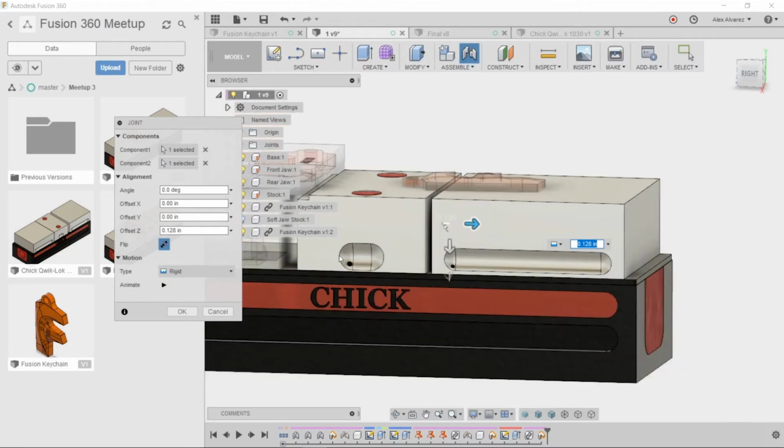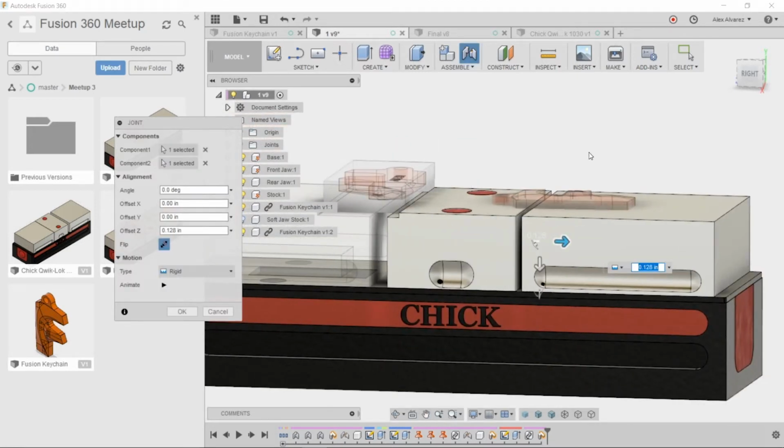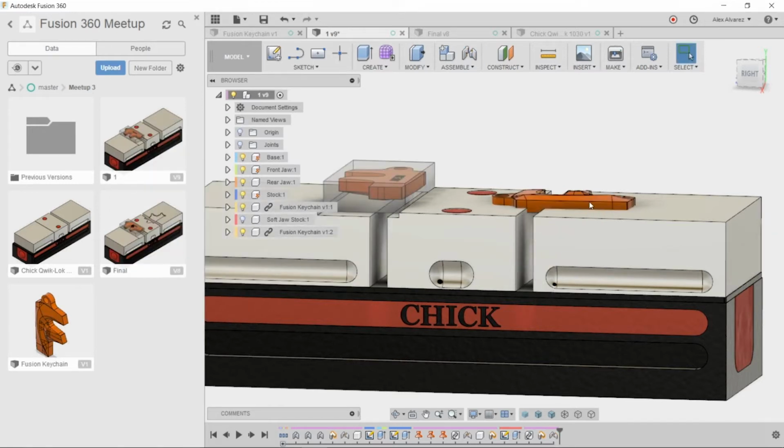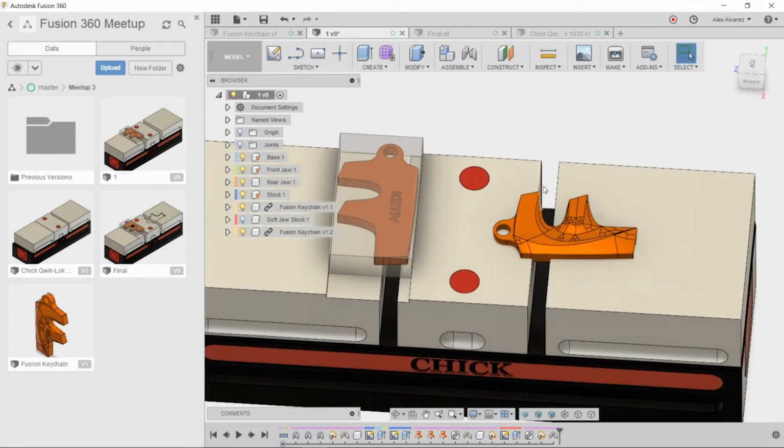So I did space this 3/8 of an inch, right? That was just a preference of mine. So I'm going to go ahead and space it 3/8 of an inch. Now what I can do here is I can add a note during the CAM operation, right? Maybe let the machinist know that when he's going to machine these soft jaws, we want to make sure that we do that 3/8 space when machining. And you can put a tool that's 3/8 inch diameter in between. Right, just have some sort of space in there, right?